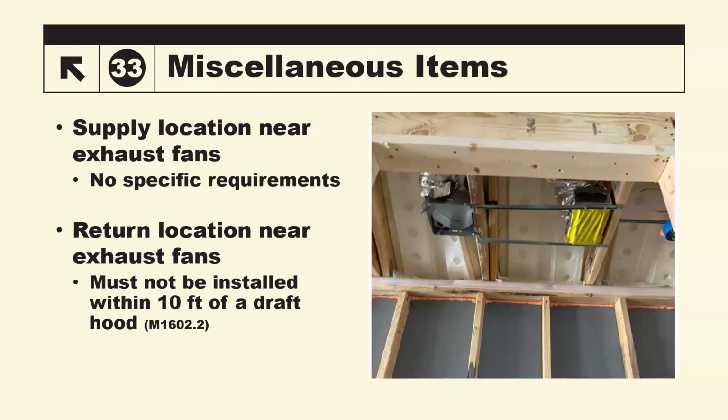And then, of course, miscellaneous item. I talked about this picture a little bit earlier. This photo comes from Logan with the city of Rowlett. Thanks to Logan for that question and photo. Basically, he was saying, hey, is that too close to an exhaust fan? And of course, we look at it and, well, that's a supply boot. That's not a return. And so according to the code, there's no specific requirements against putting supply vents near exhaust fans. They have throw and velocity to them that should make it past any 80 or 50 CFM fan. It should make it past that. This is a very small bathroom. There probably won't be an issue with it.